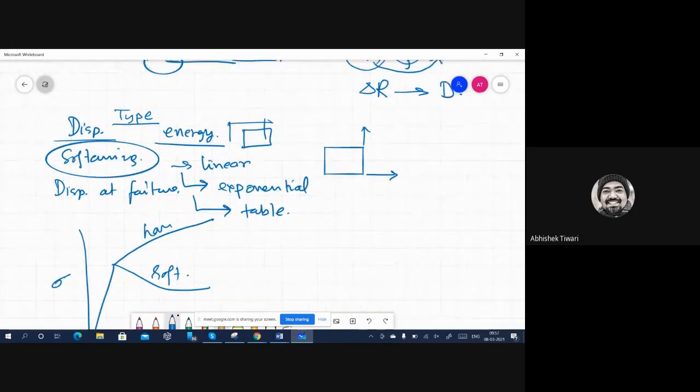So then in the displacement mode, you choose displacement, you choose what kind of softening you want to define: linear equation, exponential equation, or table. Then you have to define the displacement value at which the RBE element will fail. If I write 0.2, then as soon as this element reaches a value of 0.2, it will simply stop bearing any load. No equation will be solved for this element, and it will be removed from the total assembly of finite element analysis. So it will be just lost, gone, disappeared.